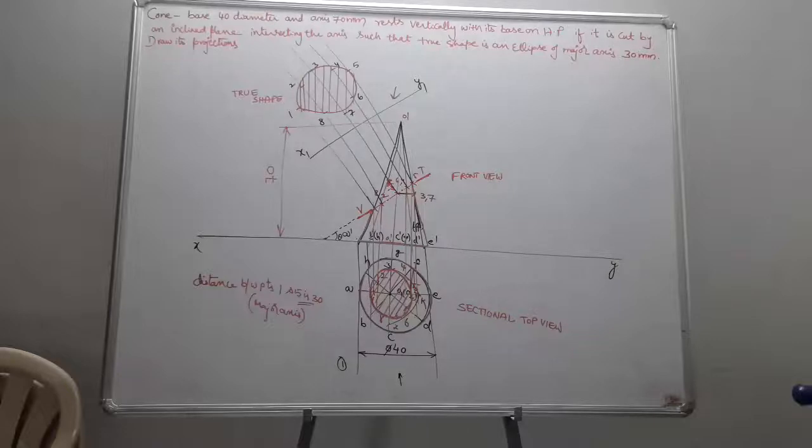I will explain. So here also the 3 comma 7 points are going to be obtained on GC. If I project those points, they should coincide with the edges OC and OG. For that, I project my points on the true slant edge, and from there I project my points to their position.